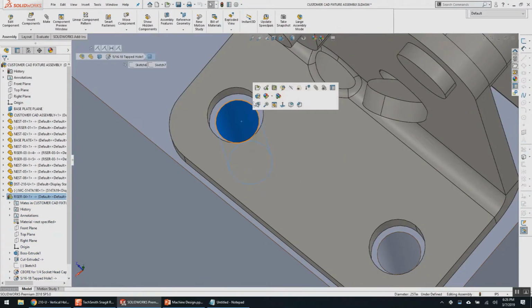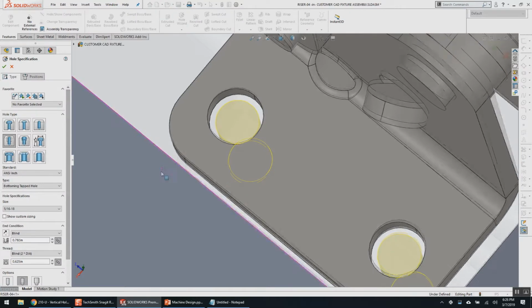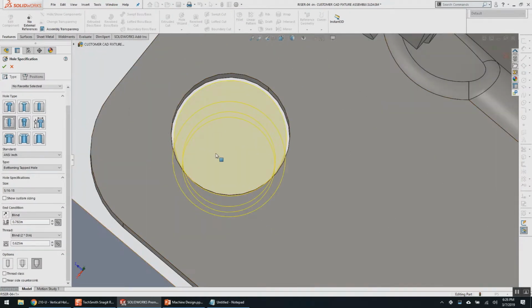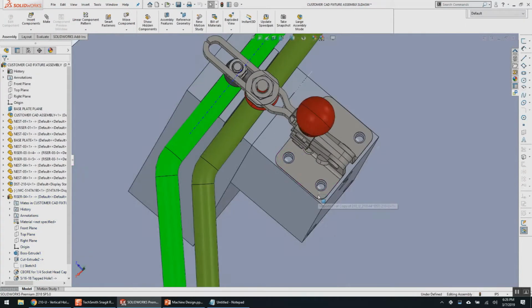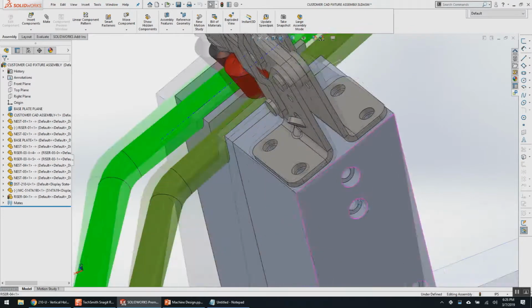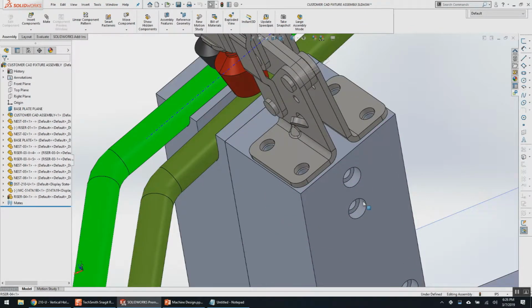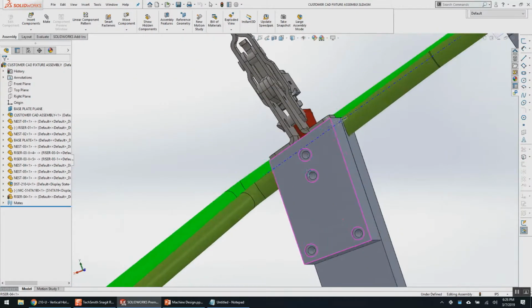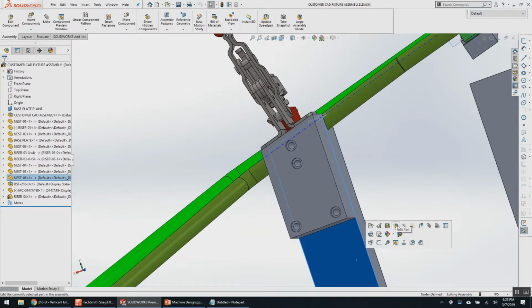Try to stick to a single fastener size per general design. And another way to check the size of your holes is pick this option, which is how much the threads will remove to make sure your bolt fits. You don't want that for final design, but it's a way to check. I try to stick with a general fastener because it's just one size bolt, one size wrench, one size whatever, unless you're bolting to purchased hardware in which the size of the bolt is defined and dictated to you by what it is that you're purchasing. So pretend that's good enough for the end customer at hand.